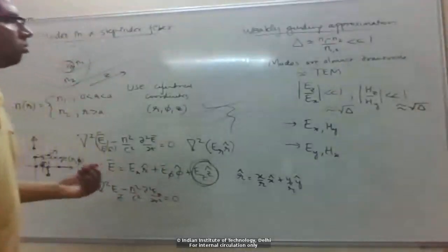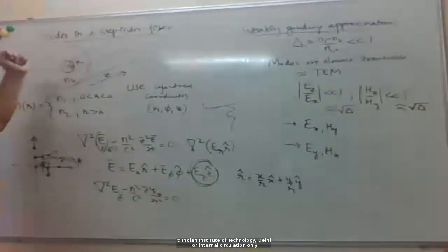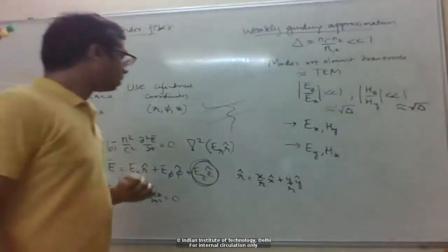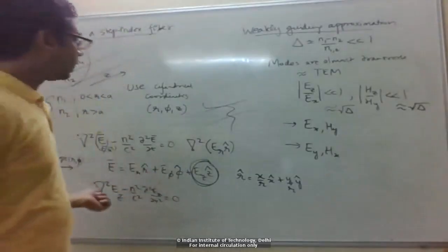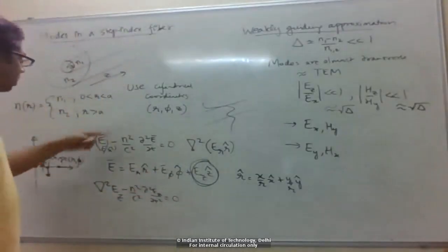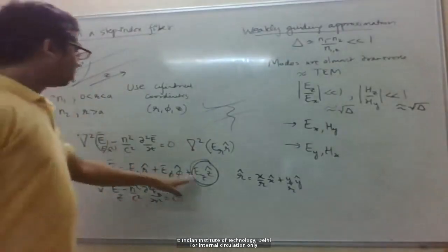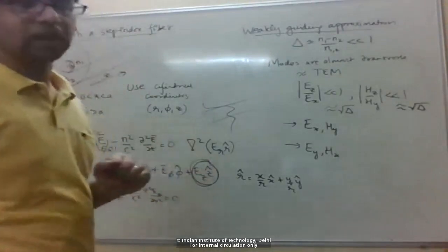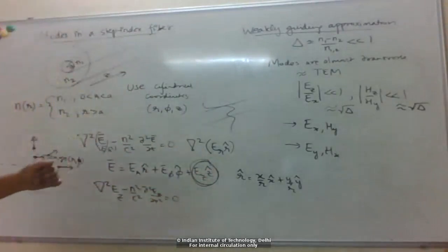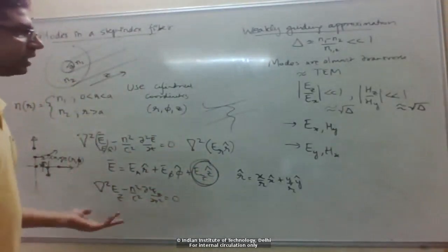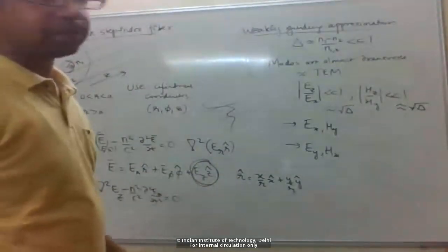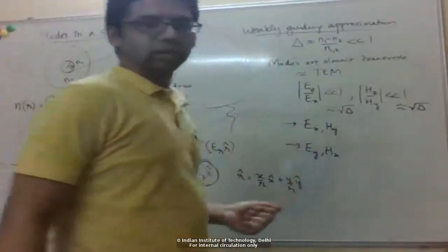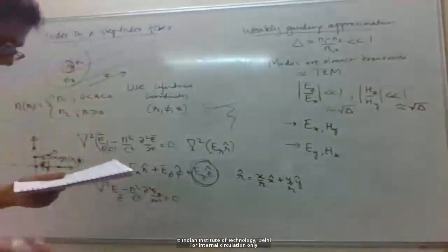But for some special cases, for example, if you're using some special fibers with larger index contrast or some other kind of application, and you need the exact modes, then as I said, we have to start with Ez and Hz and solve for Er and the other components. So the longitudinal components Ez and Hz are not identically zero, but in this approximation we can assume them to be small and say that they are zero.